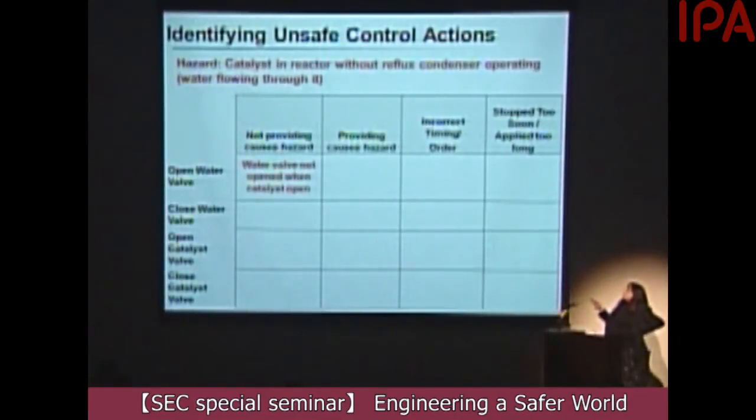What about incorrect timing or order? What about if we open the water valve after we open the catalyst valve? That was actually what happened in the accident. Stopped too soon or applied too long, well, maybe the valve opening stops too soon.